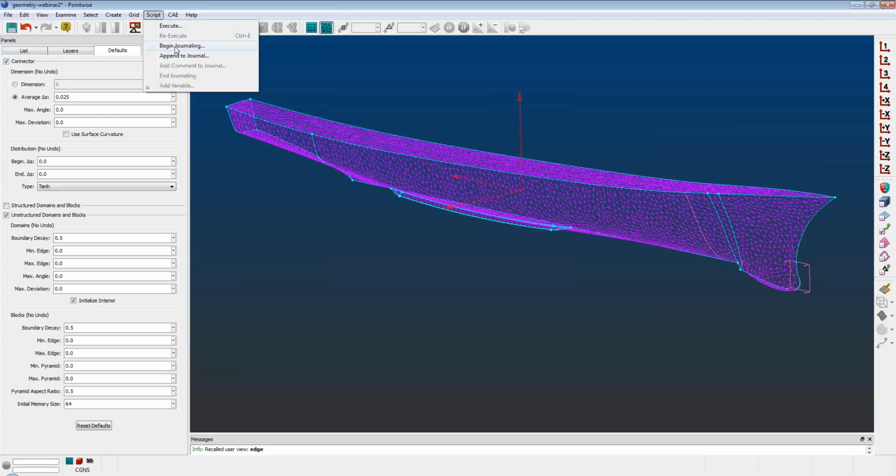And maybe I'll just take the opportunity to mention a little bit about the scripting language in Pointwise. It's called Glyph, and Glyph is really just an extension of the interpreted programming language called Tcl. So really, we're just adding functions to Tcl, and so you can journal all those Glyph commands and those Tcl commands, and then you can use it to either replay something you did before, or you can write scripts from scratch. And Pointwise can be run purely in batch mode, or you can run these scripts in GUI mode. It's up to you. It's a very flexible, very extensible method of doing scripting.